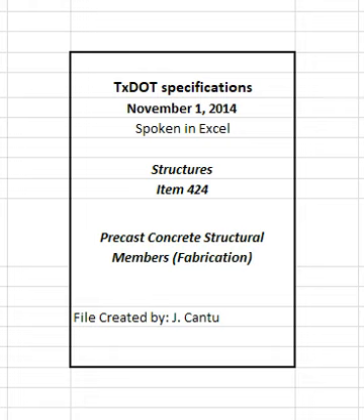Maintain concrete transporting equipment clean and free from hardened concrete coatings. At the time of concrete placement, reinforcing steel, strands, and embedments must be free of dirt, oil, or other bond-breaking substances. Place and adequately consolidate concrete while all lifts are in a plastic state. Concrete must not exhibit segregation or excessive bleeding. Minimize concrete flow lines and displacement of the reinforcing steel, strands, embedments, and ducts during concrete placement.